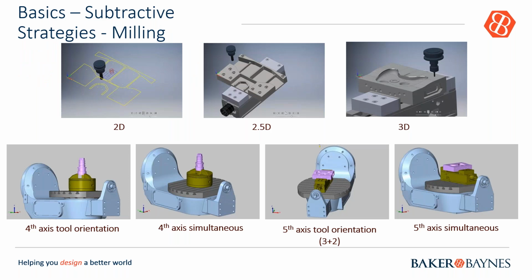So first, the workflow would be from your design to your manufacture side of it. And the two key tools used for manufacturing itself, or subtractive manufacturing, or CNC, will be HSM, that's available to you in the collection, and also Fusion. Let's have a look at HSM itself and some of the areas where it's being used. So Autodesk Inventor has CAM for Inventor, that's the Autodesk HSM plugin that installs from the collection itself.